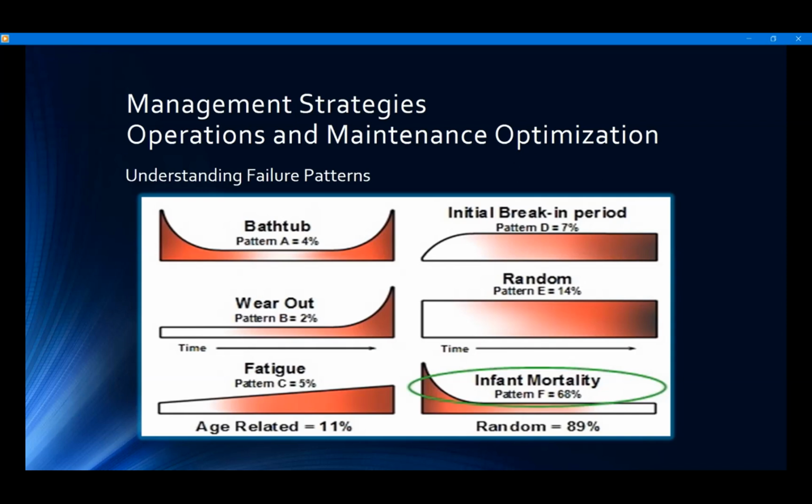These types of failures need to be detected as they are not predictable or based on a defined life. The equipment must be monitored for specific indicators. These indicators may be changes in vibration, temperature, flow rates, etc. These types of failures must be monitored using predictive or condition monitoring equipment.